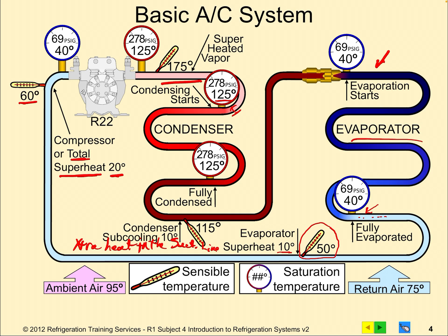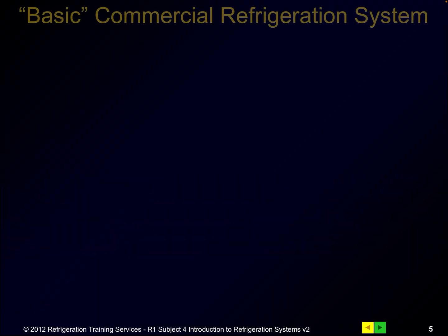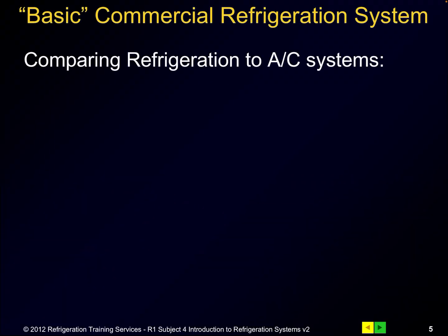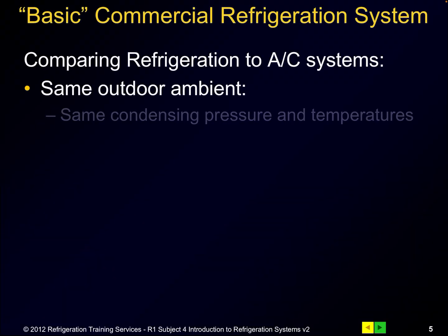And the way we're going to know it is because the actual temperature will be colder than what the condensing temp is of 125. So when we compare those two, it's showing me 10 degrees of subcooling in this example. So from the 125 down to the 115, thus condenser subcooling is 10 degrees. And that's really the whole process of how that happens on a system.